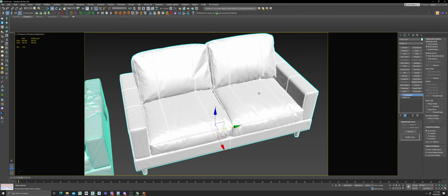In other words, it will decimate. The term here is decimation. Okay? Decimation will reduce the number of vertices in your model. Doing so will destroy the topology of your mesh. But it will try to keep the details. For example, so Pro Optimizer is here. All I have to do is calculate.